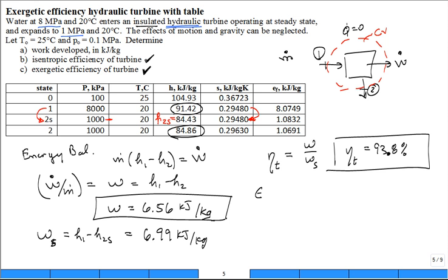We could put epsilon T. The book usually doesn't put a T for turbine, but I like to put it on there. It's the second law efficiency for the turbine. It's equal to the work that you actually get out divided by the change in the flow exergies. Now, I computed these and put an extra column for the flow exergy because it's just another property, is it not? And this was computed in Excel. True? You could kind of see that.